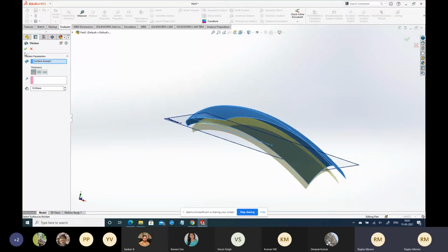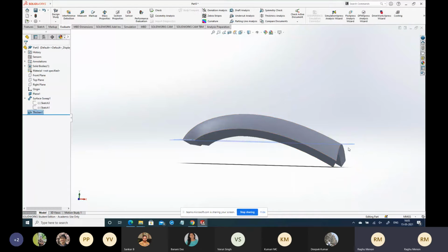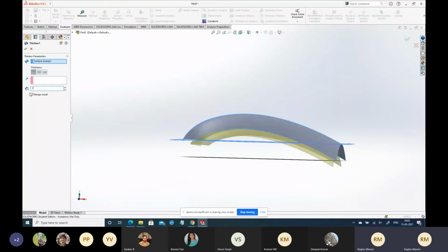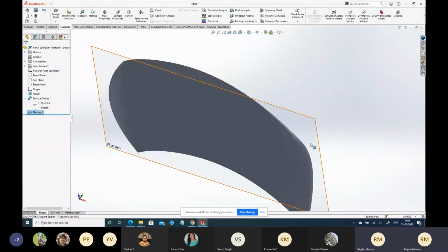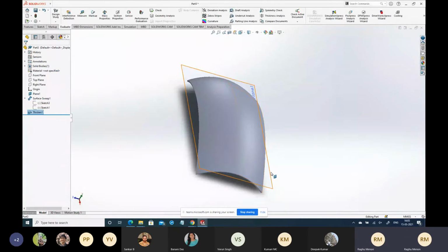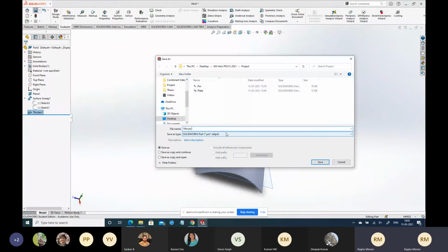And just to show you the thickening surface, I'll make it elaborate, make it a 10 mm thick surface. No mouse cover will have such a big thick thing. It'll usually be say 1 or 2 millimeter. So let me just put for say some 1.5. You will not see it, so for the sake of demo, I will make it 2. Okay. So now you have a thickened part. Now you can actually create something else, cut it, then you'll say save. I'm going to say top cover.